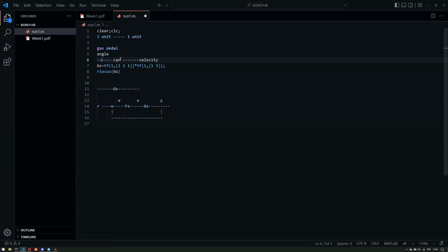Here, we will have this unit feedback, and our reference will be the same unit as the output y, because we want to alter the behavior of the car in such a way that we can give it a reference velocity, and the output should eventually have the same velocity as the input. So this is called reference tracking. We will provide a reference. The system should track that. So this is basically the first aim in control system design that we focus on in this course.